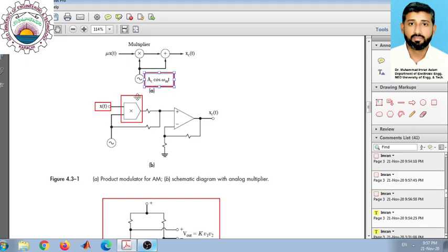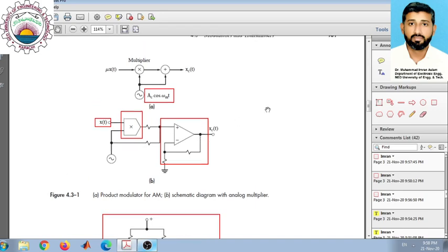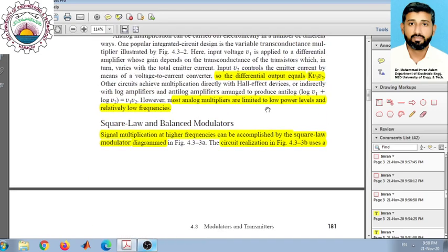So first we take the log of these two by using one of the op-amp configurations that is based on the logarithmic output. So we can set it to get a logarithm of these signals. So once we get the logarithm, then we pass it through an adder like this one, and then we perform an anti-log operation here.